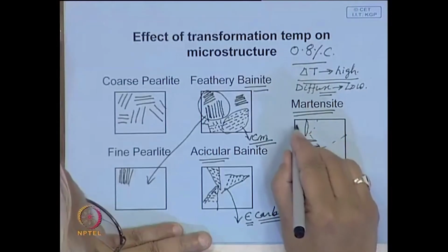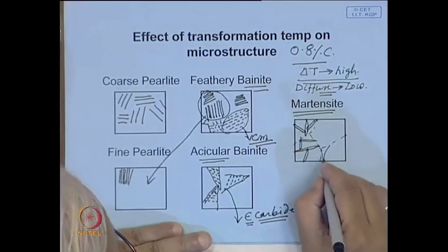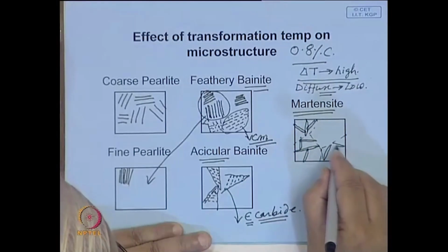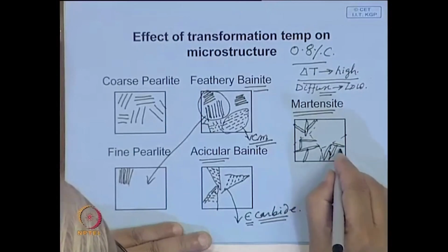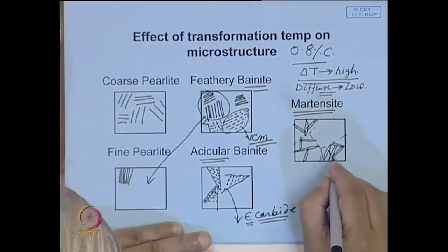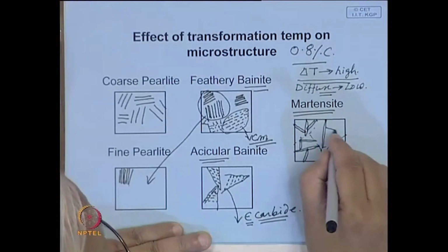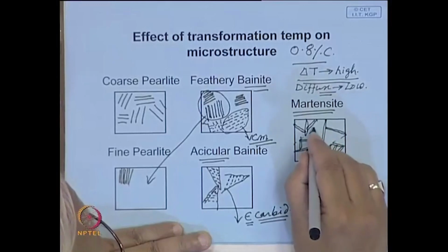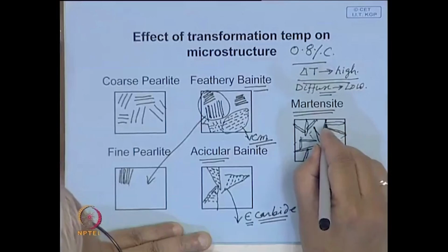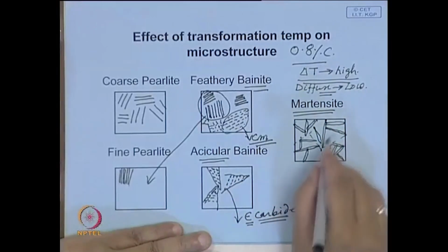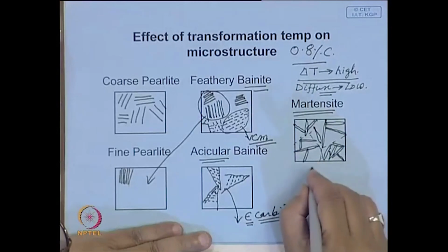They cannot cross the grain boundary, but these are single phase structures. Their fineness will depend on how large the austenite grain is. If grains are coarser, you can even see these needle like structures in optical microscope, and this type of structure is called martensite, and there is no precipitate here.